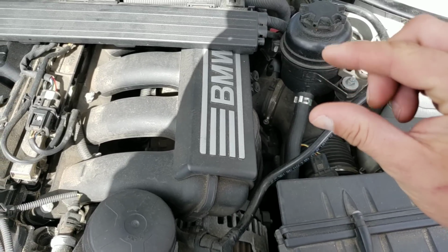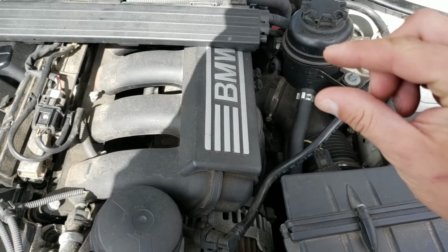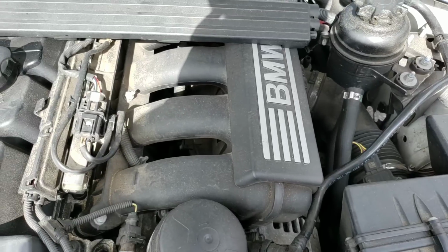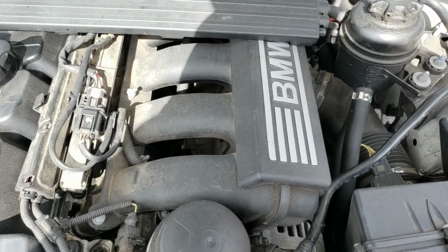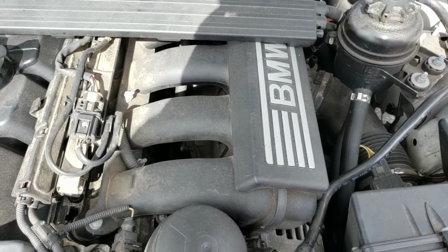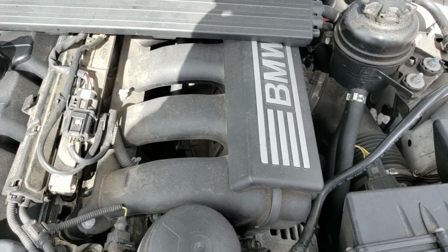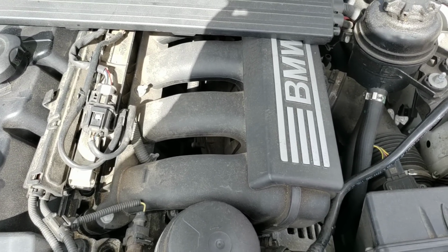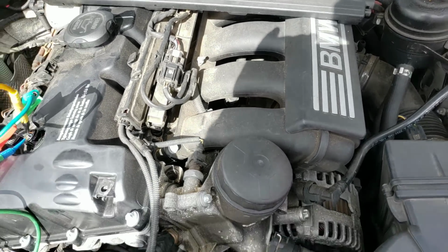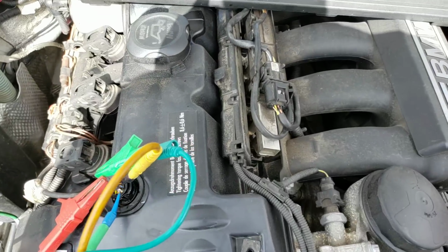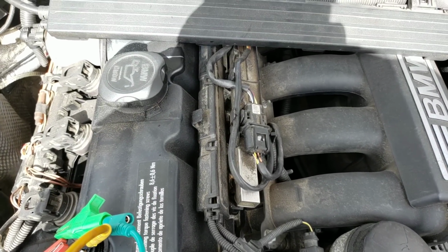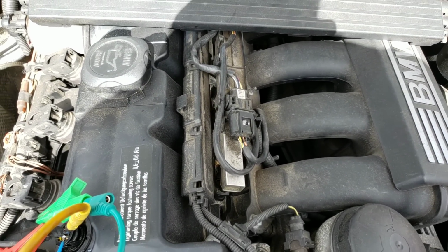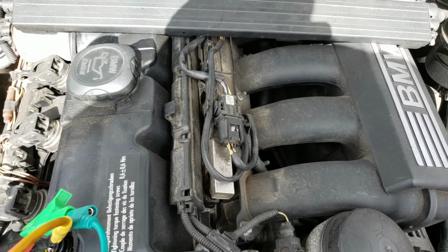So as it wants to fill the cylinder with air, we're actually changing that valve lift and allowing that air to get into the cylinder. So just a normal pulling down of the crankshaft, bringing the air into the cylinder and opening the valve X amount, tells it that it's going to fill the cylinder with X amount of air. That's, in a nutshell, what this system is doing. This has variable valve timing and also has variable valve lift.